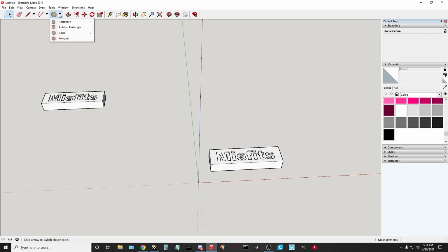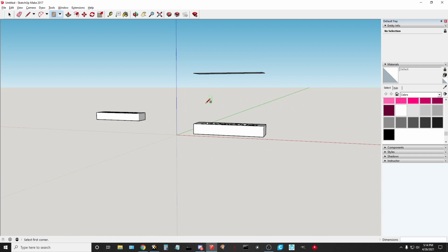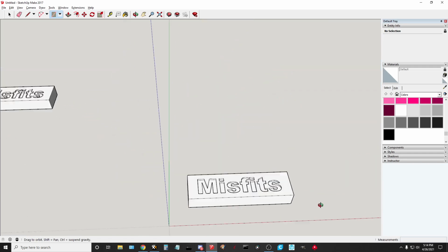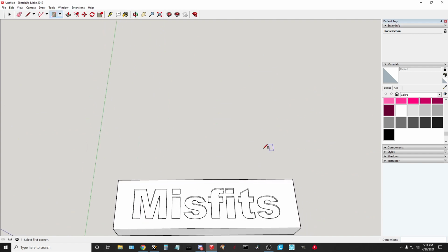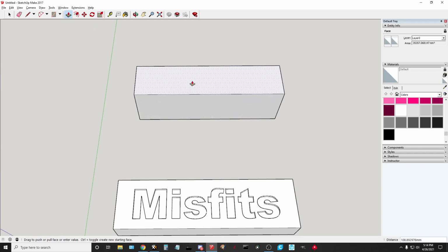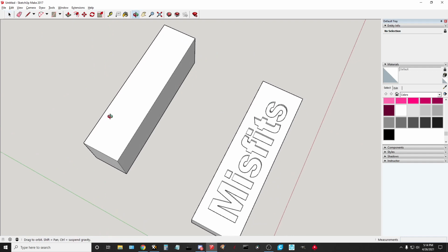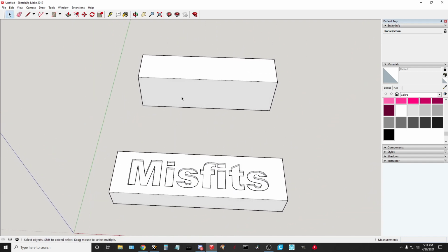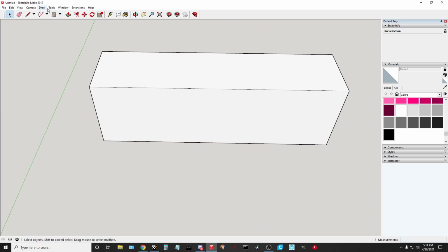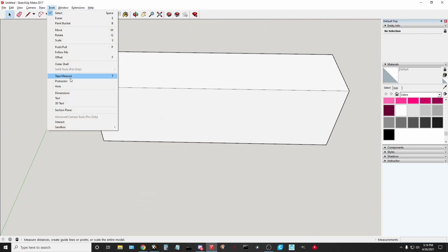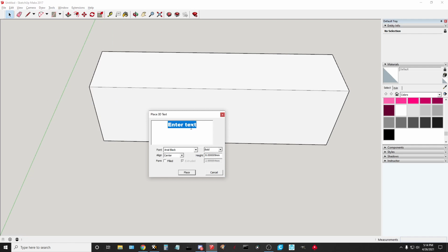Now you can also bring that text up. Move that down real quick. Oop, look at that. So I wasn't in the right plane. So let me get a little closer here. Okay, just want some thickness. You can do it on the face, whatever you want. So down the 3D text, we can do all caps, Discord, we'll call it, because we all like to be there. We can do filled, extruded. Now it's going to make the text.